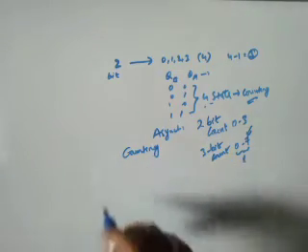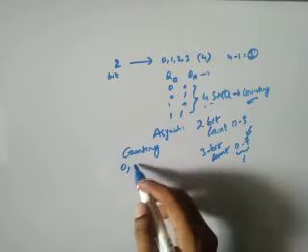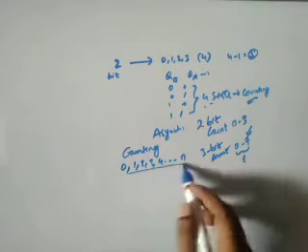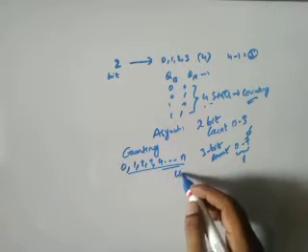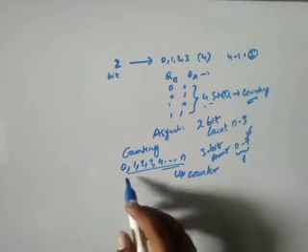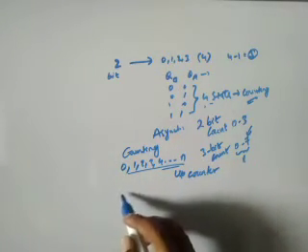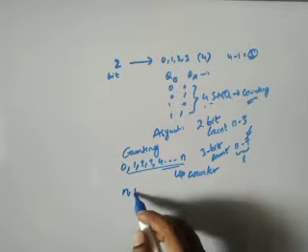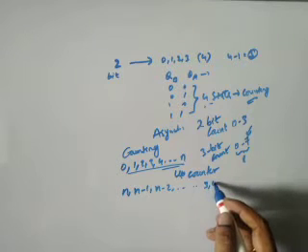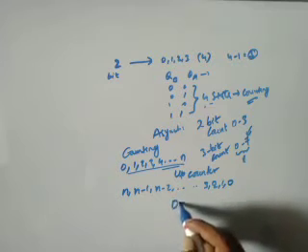either in ascending order or descending order. That means we start with 0, next 1, 2, 3, 4, up to n. This is called an up counter. The number is increased one by one. Next, coming to the down counter, we go with n, next n minus 1, next n minus 2, likewise down to 3, 2, 1 and 0. This is called a down counter.